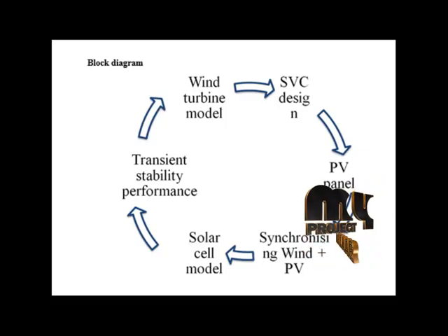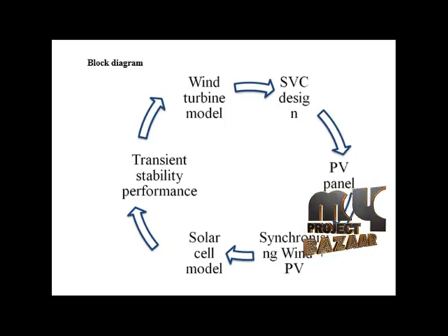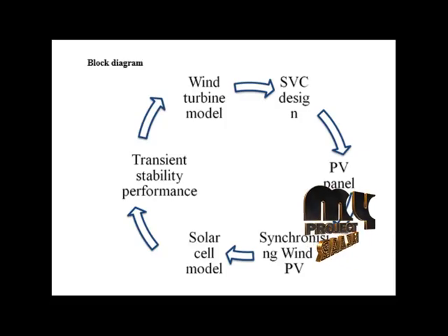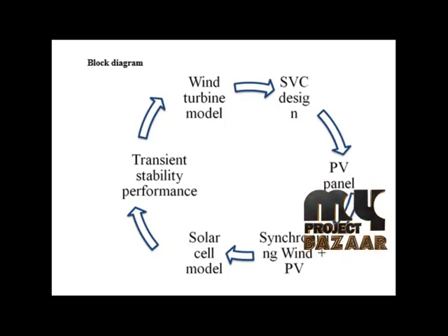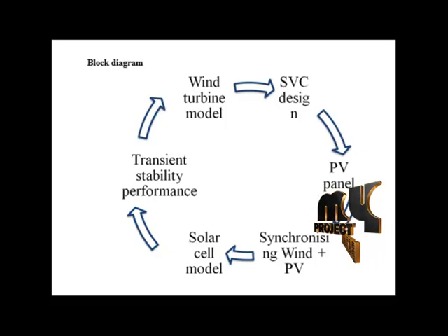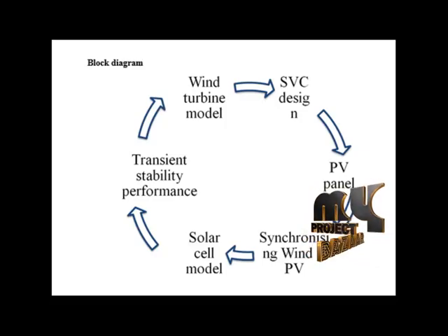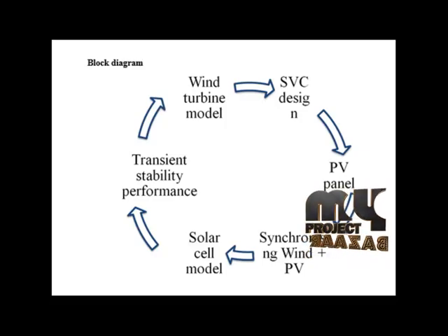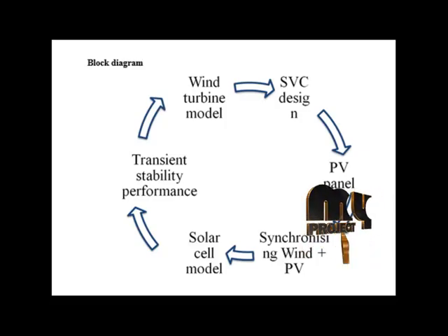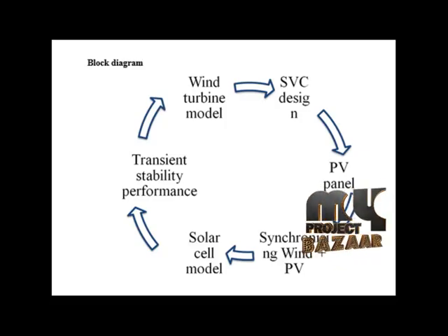Then the reserve of the large rotating machines such as synchronous condenser or switched capacitor banks. The SVC is an automated impedance matching device designed to bring the system closer to unity power factor. SVCs are used in two main situations: connected to the power system to regulate the transmission voltage, transmission SVC, and connected near large industrial loads to improve the power quality, that is industrial SVC.